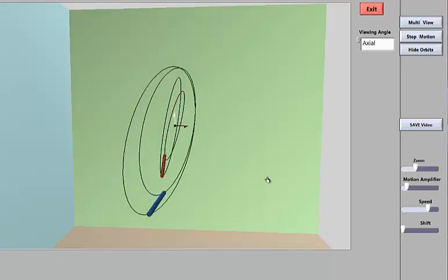An old saying is that what goes around comes around is the characteristic of imbalance, because you can imagine a weight going around, so it should have roughly the same measured vibration all the way around. So this kind of confirms what we saw earlier, that the drive end, the blue one in this case, seems to have more of an imbalance characteristic from its phase relationships, whereas the red one seems to have more of a misalignment characteristic from its phase relationships.